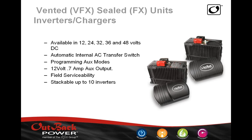In the case of backup, standalone, or off-grid inverters, we have essentially two models: a vented model, which is on the top, and a sealed model. By sealed, I don't mean that it's a NEMA 3 or higher. They're both NEMA 1. But sealed is the unit you'd want to use if you were near the ocean or dealing with a lot of insects, because our inverters are installed throughout the world.